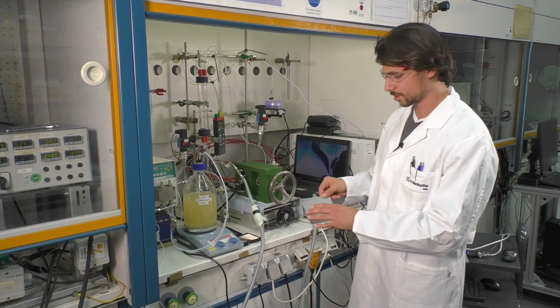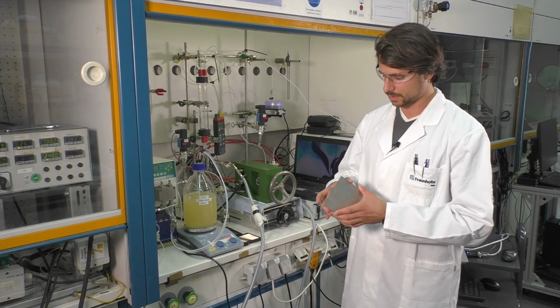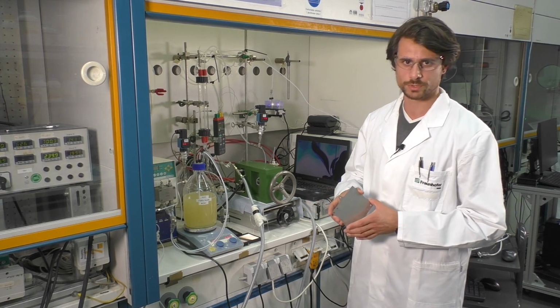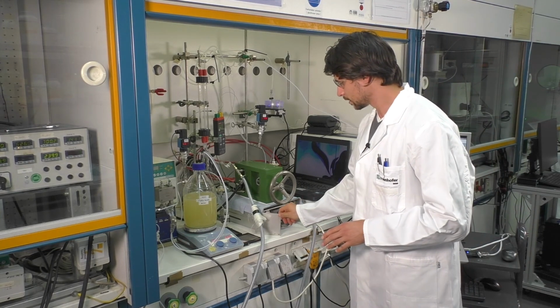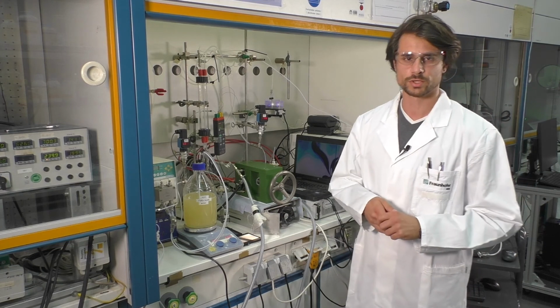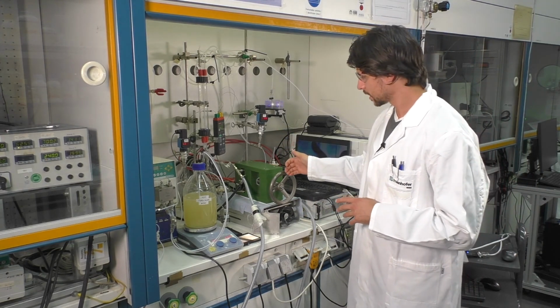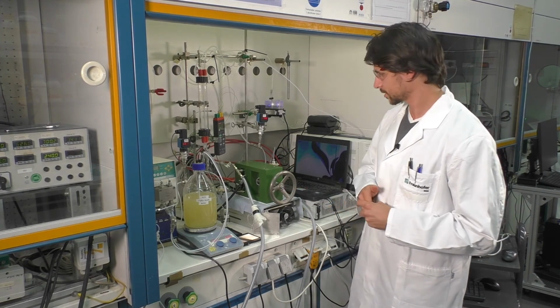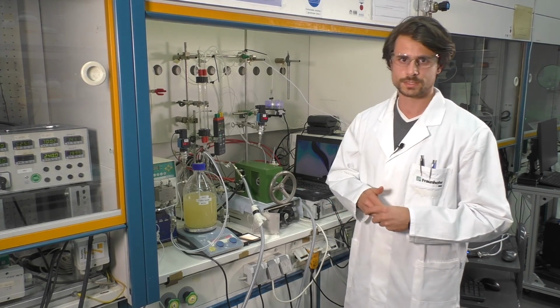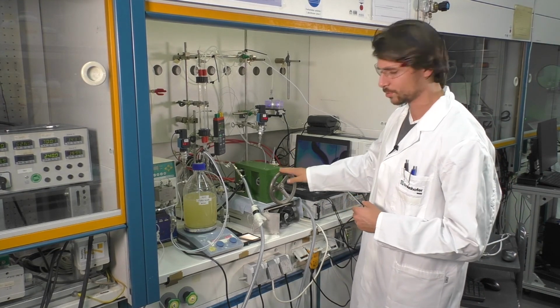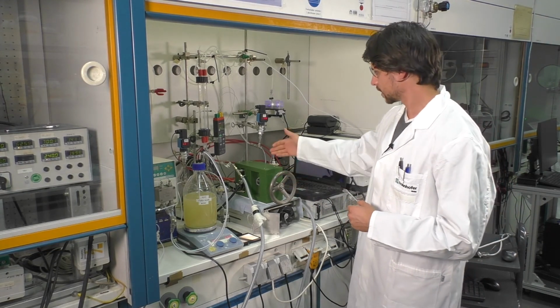As a counter electrode we use stainless steel. This is coated with nickel to prevent any corrosion during the process. The electrodes do not need screws, so this modular design is very flexible. We can easily scale the reactor up or down and use several numbers of electrodes, and leakage is prevented with seals in between the electrodes, and we can press them together so that we have a complete system.